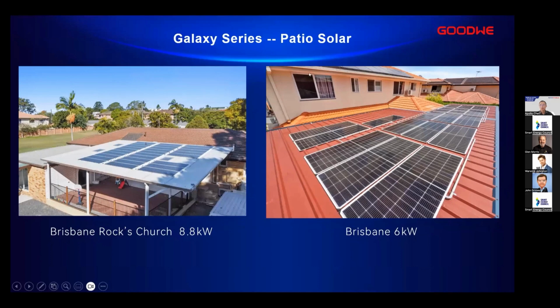As you may already be aware, there is an existing 6.6 kilowatt system on the rooftop. The reason he liked to expand the system is that he replaced his old hot water boiler with a new electrical boiler. The bill rose significantly after that. Because there are no other suitable roofs, and he doesn't want to sacrifice generation by using the south face roof, we proposed he use this north face patio. And there's no penetration, which means there are no water leakage concerns for the owner.